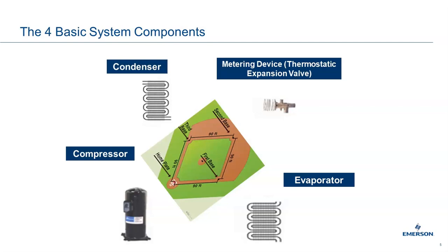In other words, if you had an air pump that you were filling up your tire with, if you cut the hose off of it, the valve that you put on the Schrader valve, and it was just blowing outside, you would never be able to build up pressure. That pump would just keep running and running. So this is our pressure drop, okay? So it causes a pressure drop. And like I said, it controls the amount of refrigerant going to the evaporator, all right?